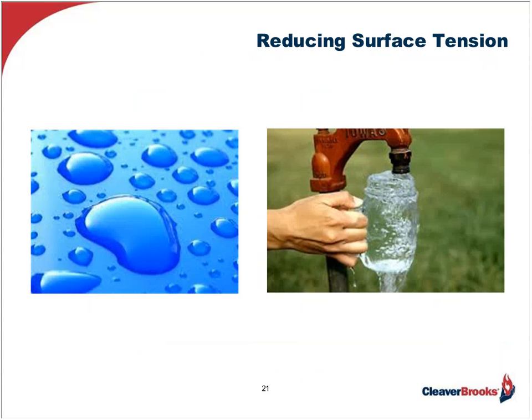All right, so much for the why of deaerator science. Now let's spend the balance of our time looking at the what and how factors. Firstly, we need to understand and appreciate the complexity of water, not only its constituents, but its characteristics. For instance, water possesses a high degree of surface tension, which tenaciously holds things in place unless a surfactant is applied or some other means are imposed on the water to reduce the tension. And that's exactly what deaeration does.